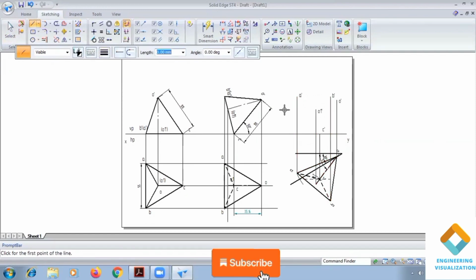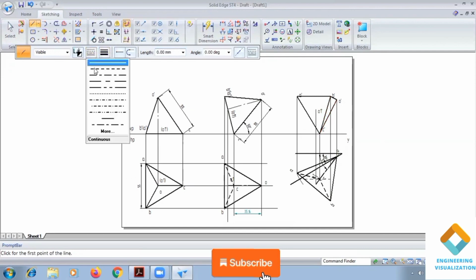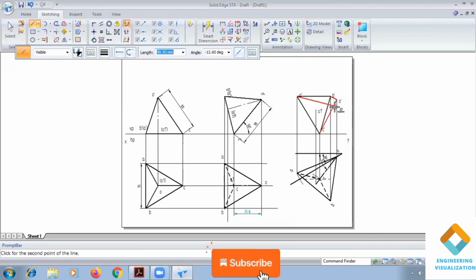After writing the notations, you can join it first. Join the triangular face and then the slant edges. If any of the slant edges pass inside, that will be a dashed line. Passing outside means it is a continuous one. So the dashed line is from this end to here. And then finally we need to draw an axis. That completes the problem.